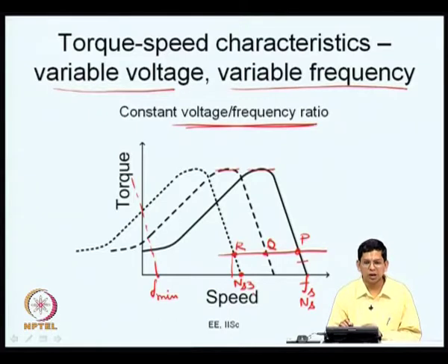So, there is something called slip compensation that you can do, which will make sure that the machine can really run at 750 RPM. The synchronous speed of the machine will be equal to the actual speed at which it should run plus the so-called slip speed. So, that is called a V by F drive with slip regulation.